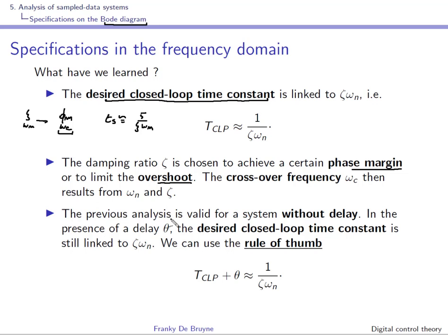Very important is that the previous analysis is valid for a system without delay. In the presence of a delay, things are a bit more difficult. And if this delay takes substantial values with respect to the main time constant, it becomes more and more difficult.